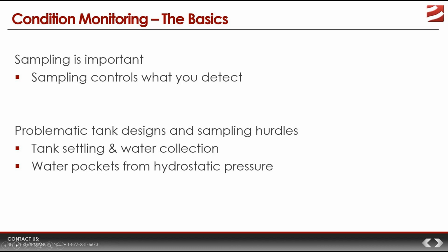Now, when you're putting in underground storage tanks, the regulations dictate that the tank has to be trimmed by the fill end. That means it either has to be level or slightly lower on the fill end. But because of their weight, tanks almost always settle into their backfill, and many times they settle in certain ways that influence where the water is going to collect.